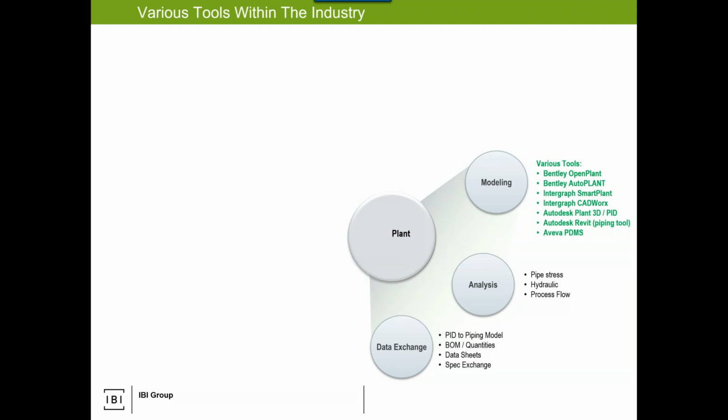Water is thrown up into a water tower because then hydraulics can let it flow with a high pressure into the distribution network to your homes. When we're pulling water in from the lake, we're very deep in a lake. You might be pumping it a couple times, and once you pump it high enough into your treatment plant, it'll naturally flow through the system to get put into distribution. So, you know, there's that there. From a BIM coordinator perspective, you'll hear that and say, how am I supposed to know that? Like, you're not. You're not supposed to know that. But you might get exposed to that.